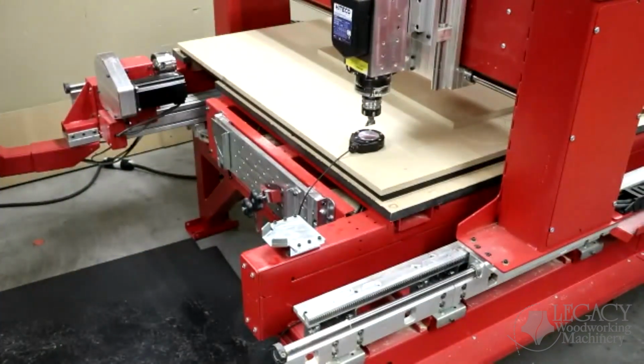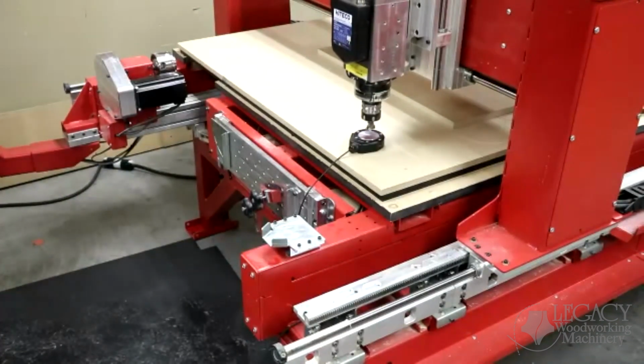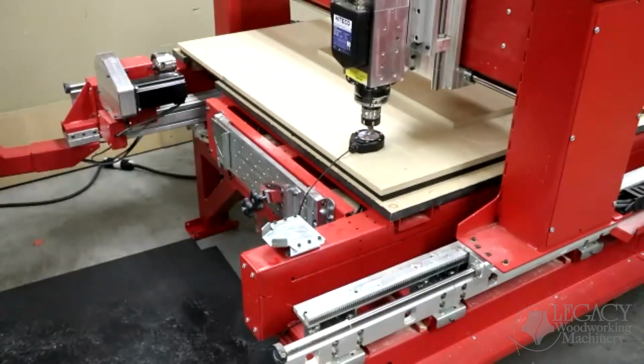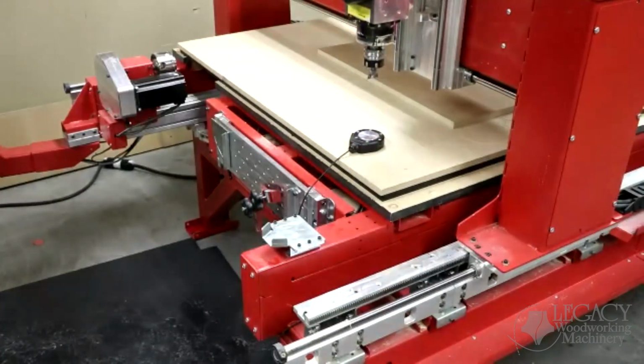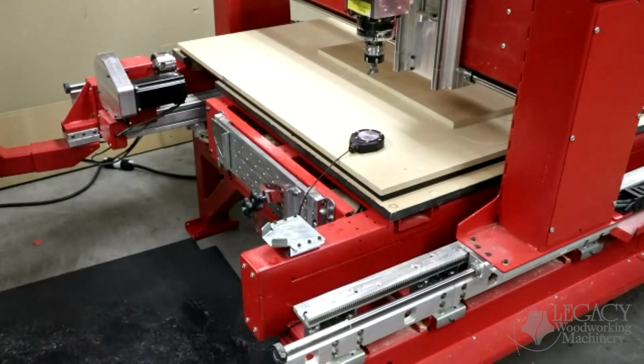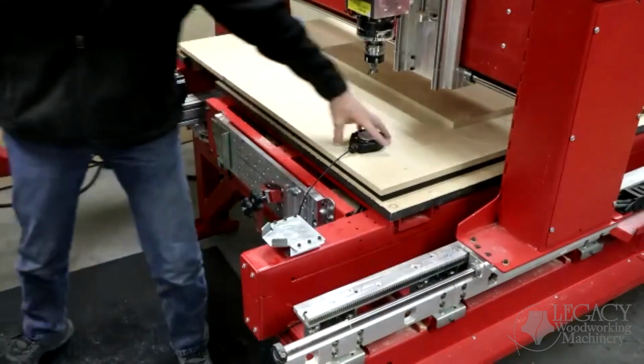Okay, so when I do a multiple tool touch off, you're going to see two things. Number one, if it's over the pad, it doesn't know where the pad is, so we cannot do a rapid Z. So when we hit this multiple tools, it's just going to probe very slowly until it touches. So if you've got it at the very top, it can take quite a long time to get all the way down there. So that's why I lower it down when I'm touching off here, to center it and to get it close.